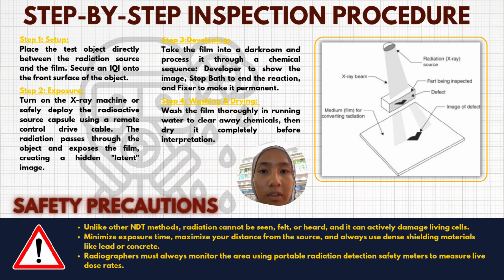The last step is washing and drying. We have to wash the film thoroughly in running water to clear away chemicals, then dry it completely before interpretation.